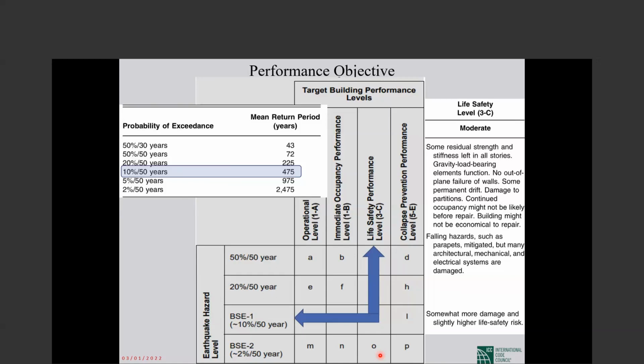Explicitly, you check the level of damage the building will have under that earthquake. You don't just increase, for example, the importance factor or the base shear and hope that the behavior of the building goes from life safety to, for example, immediate occupancy. We hope, we don't check.